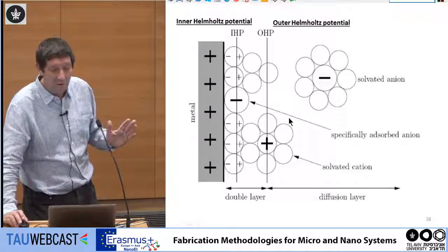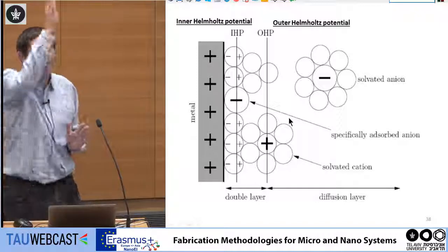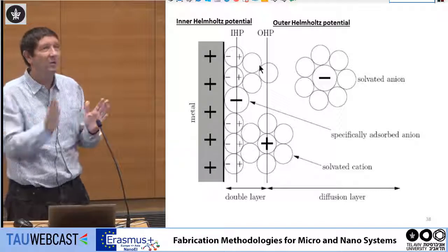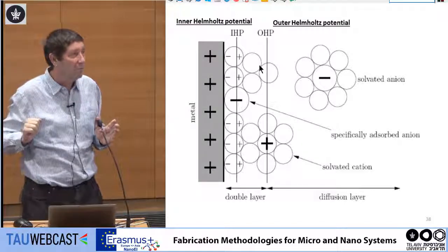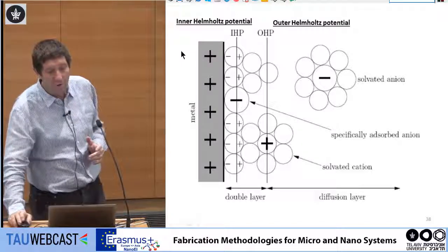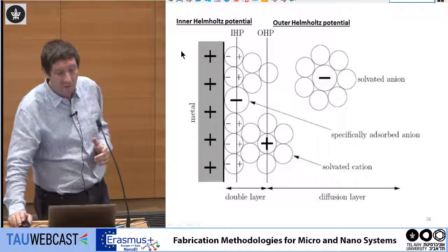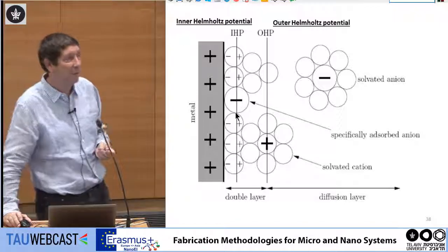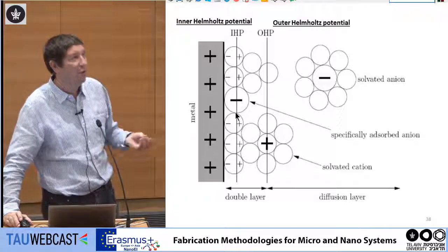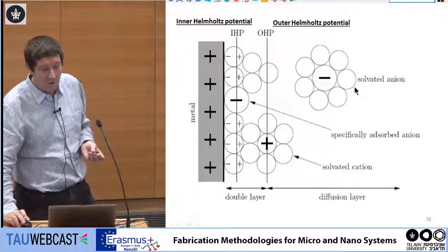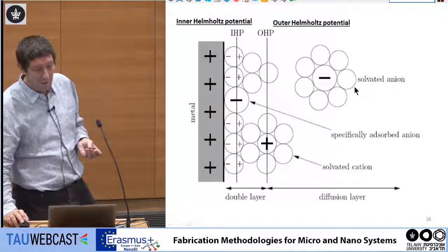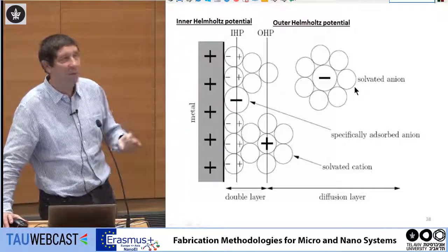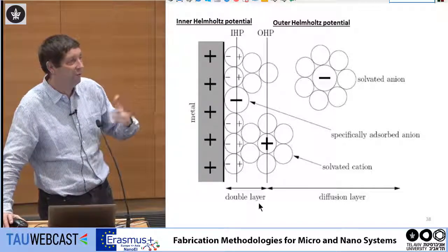Now, this is a very symbolic notation. Of course, in real life, there's no sharp boundary between the charged and the neutral area. The transition is smooth, and the width of this layer is the Debye length in this material. If you remember this from Introduction to Semiconductor Theory, it's the same phenomenon. This is the edge. You have a space charge here, and this is called the double layer. It's equivalent, in semiconductor physics, to an accumulation layer or inversion layer.